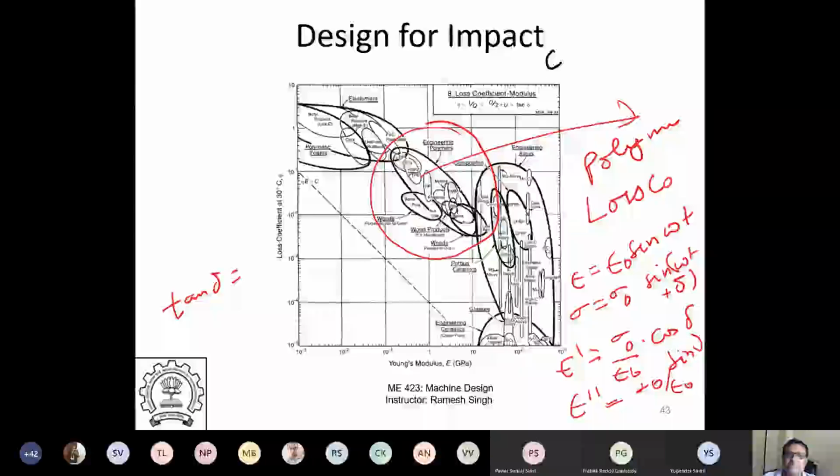Because boron carbide again is a very hard and brittle material. So you use boron carbide as a strengthener. People use ceramics also, multiple ceramic plates, because that can take impact. And because there are multiple plates, there would be energy dissipation. If instead of taking one plate, you pack 5 plates there, these 5 plates will have internal movement, and that can actually kill the impact.